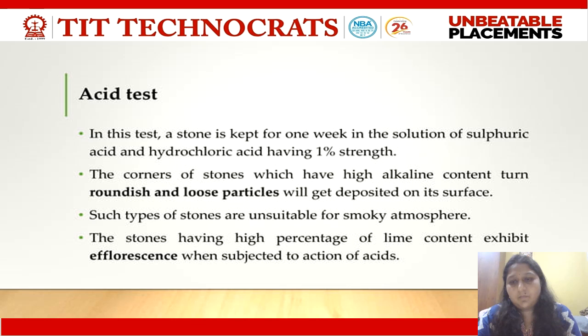After the 7 days time span and removal of the stone from the solution, if the edges and the surface of the stones are as we have placed them, it means we have no lime present in the stone and it is good enough. Otherwise, if its edges have been broken and we get a thin layer of fine particles in the solution, it means there is more lime content, which may exhibit efflorescence when subjected to the action of acids.